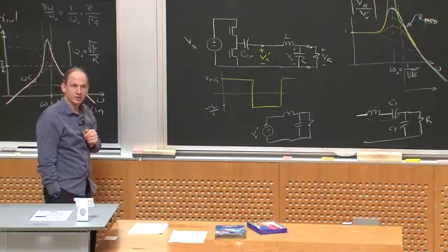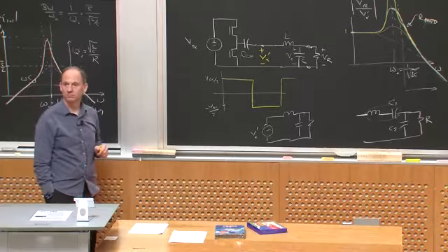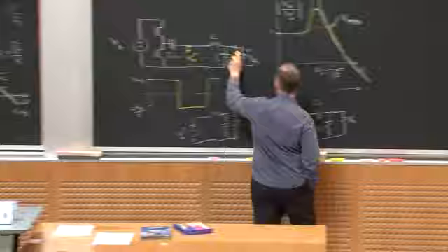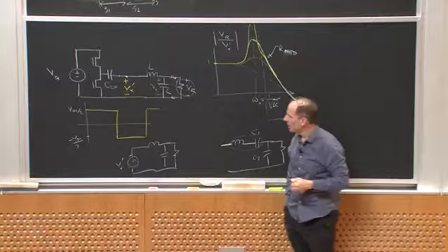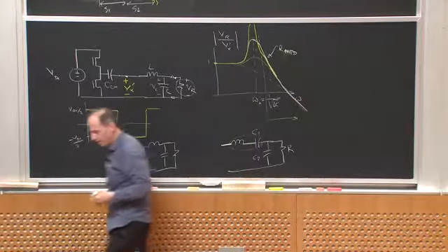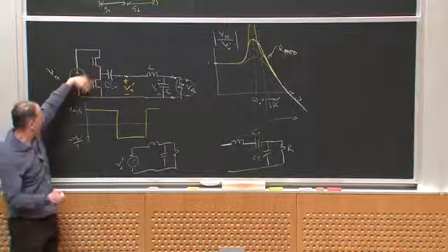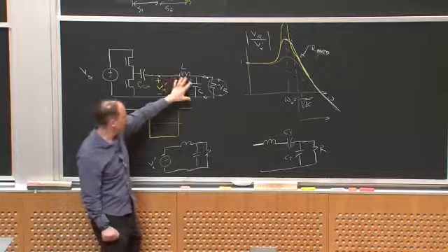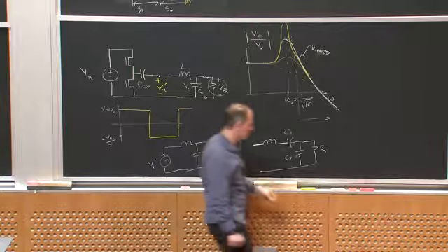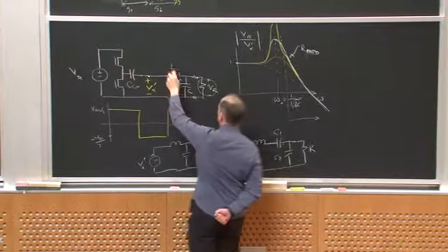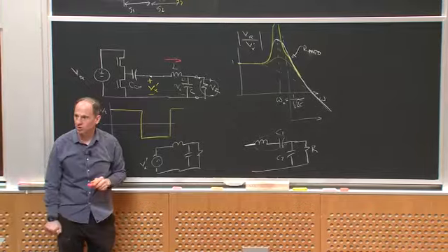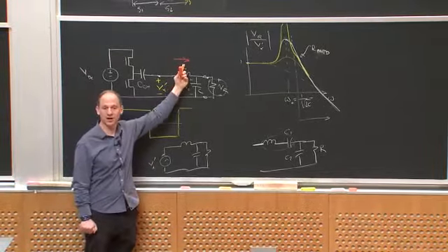Another example, however, is just straight DC to DC conversion, right? I didn't say what this resistor was, but imagine I use a network like this one. I take DC, I chop it up, generate a square wave. If I have a high Q tank, then this current becomes sinusoidal or close to it, and that's where I make my fundamental harmonic approximation.